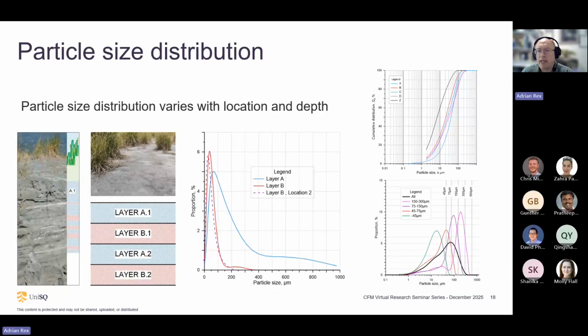Okay, so what is happening to the particle size distribution? We see in certainly a lean slurry deposit system, we see distinct layers. You can see layers here in the cut I put through the ash pond, and there's a mechanism there of sedimentation of particles being pumped.